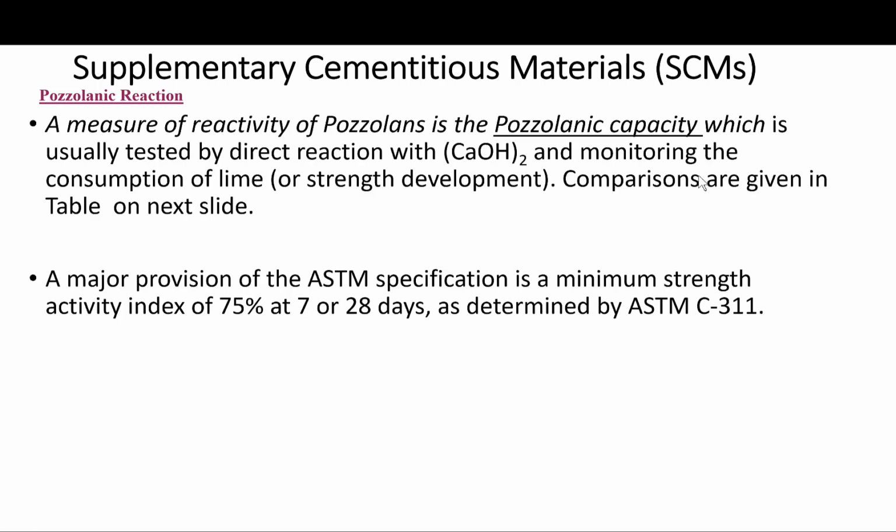So a measure of the reactivity of the pozzolan is the pozzolanic capacity, which is usually tested by direct reaction of calcium hydroxide and monitoring the consumption of lime or strength development over time. Okay, so comparisons are given in this table here. I'll show it in a minute.